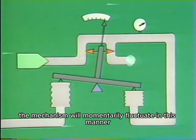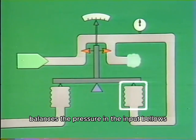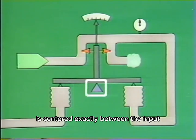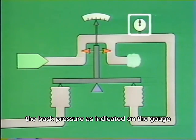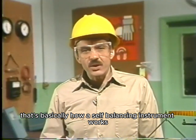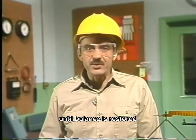The mechanism will momentarily fluctuate in this manner until the instrument eventually reaches a balanced state, where the pressure in the balancing bellows balances the pressure in the input bellows. The pivot in this example is centered exactly between the input and balancing bellows. So when this instrument is balanced, the back pressure, as indicated on the gauge, is equal to the input pressure. Well, that's basically how a self-balancing instrument works. When an unknown input is applied, an error is detected and the output is automatically changed until balance is restored.